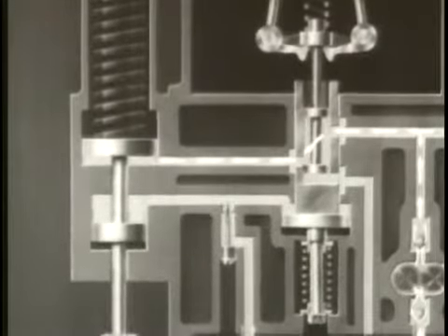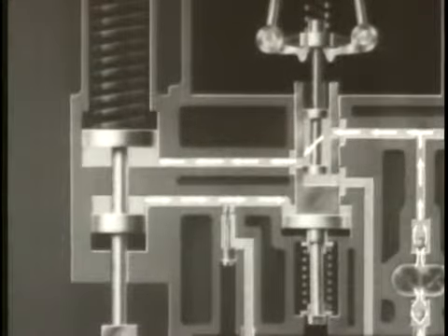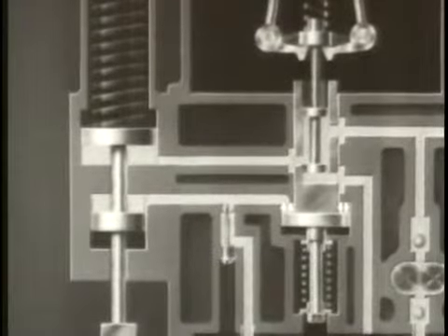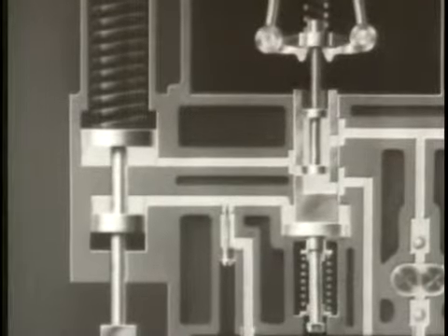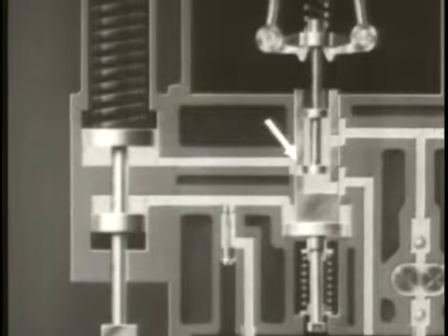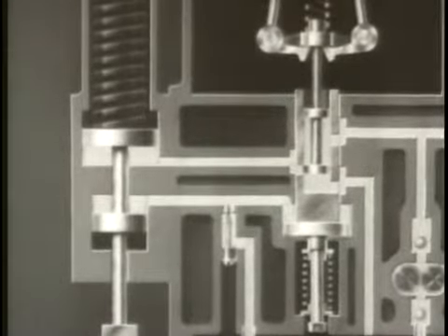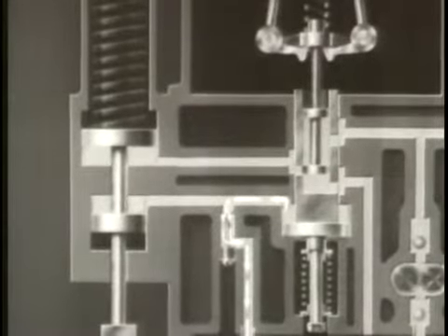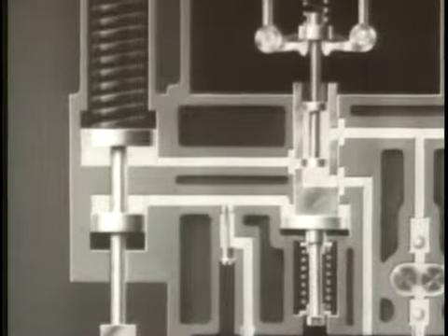When the engine speed drops below the set rate, the actuating compensating plunger moves upward with the power piston. This increases the oil pressure above the receiving compensating plunger, which therefore moves down, carrying with it the pilot valve bushing. As before, the port leading to the power cylinder is closed. The excess oil in the compensating system now drains out through the needle valve as the spring returns the bushing to its central position.